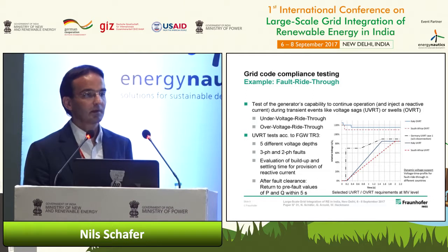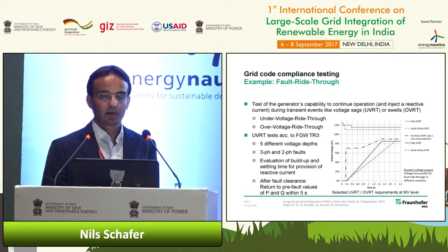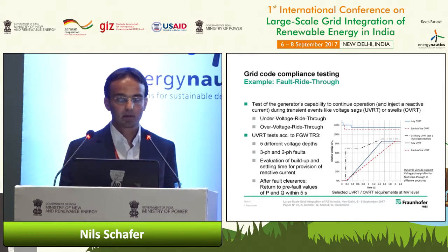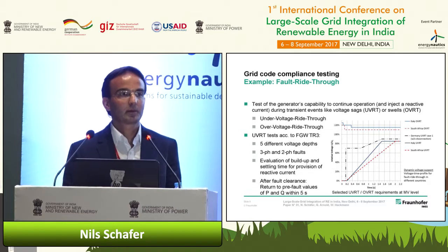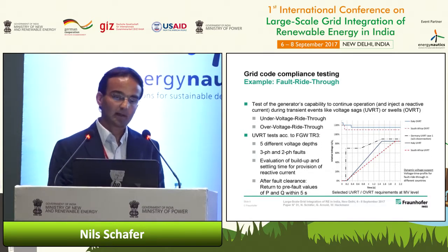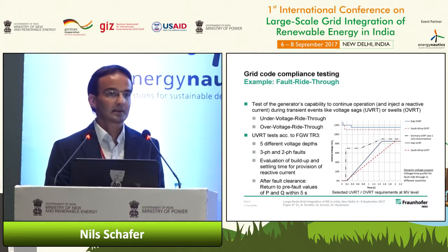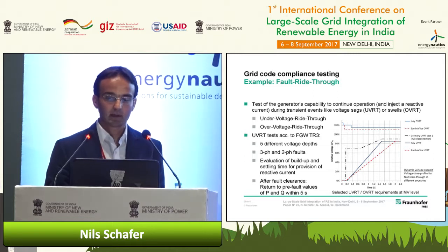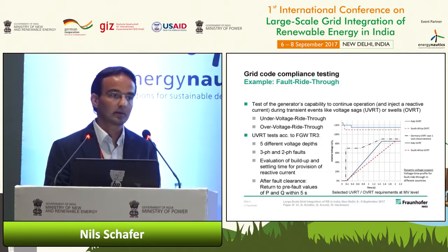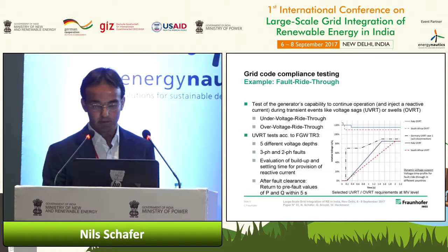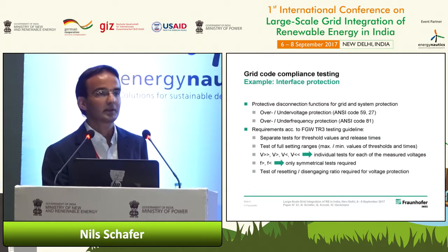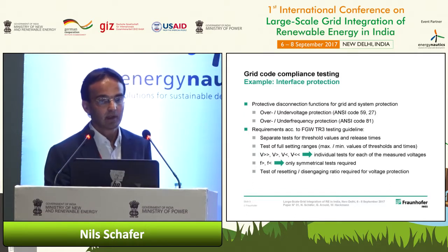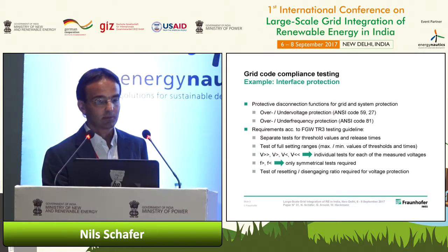Also, a requirement is defined for the time after the fault. Active and reactive power have to return to the pre-fault values within 5 seconds. In other countries like Italy, this time is much lower. I think in Italy it's 500 milliseconds. So requirements really differ. For interface protection, for over-under voltage protection and over-under frequency protection, there are also tests to be done.